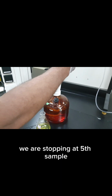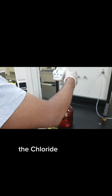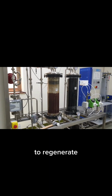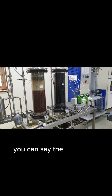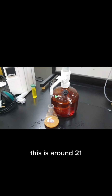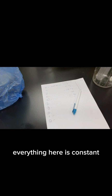This is the last, 5th sample. We are stopping at the 5th sample, and then we will see how to calculate the chloride ion in the water, because now we are just noting down how much titrant is consumed to regenerate or do the backwashing for the activated carbon, the column or the filters. It's consumed around 21 ml of the titrant. The reading here is constant.